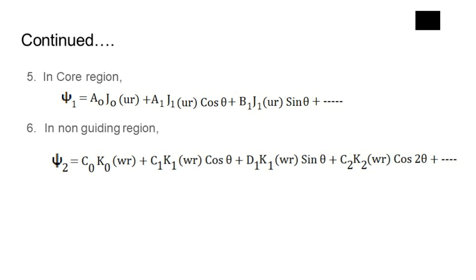It must also be remembered that if we take more points on the boundary, the characteristic equation will be more complicated. We can obtain the cutoff equation again by setting w equal to 0. So in this way, we can determine the possible number of modes sustained by these non-circular waveguides, which are more complicated. We cannot solve these geometries easily using the analytical method. So the point matching method is very useful in that case.